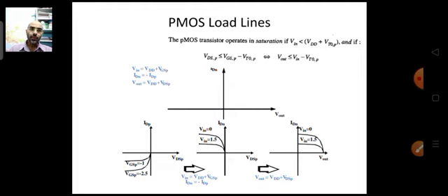So what we do is, you see, one of our transistors, NMOS, is working as a driver, whereas the upper transistor PMOS works as a load, in one situation. Whereas in the other situation, when your input is low, PMOS becomes the driver, whereas the NMOS becomes the load. And if your input is high, then the opposite, which I have told earlier. So NMOS becomes the driver when the input is high, and PMOS becomes the load.